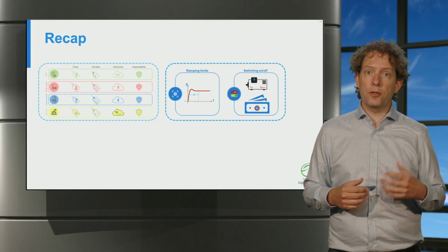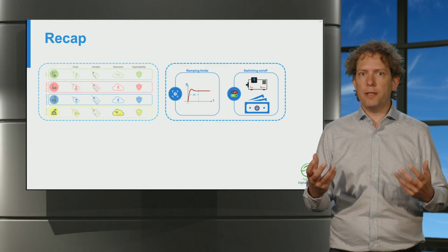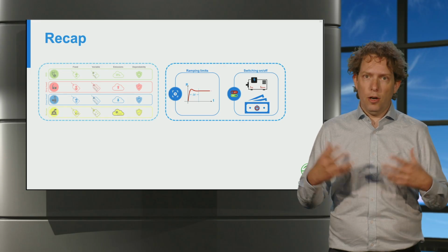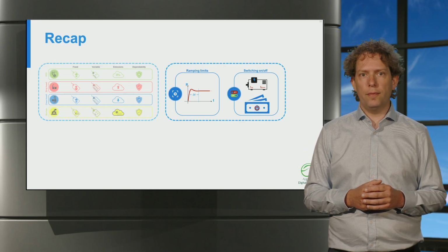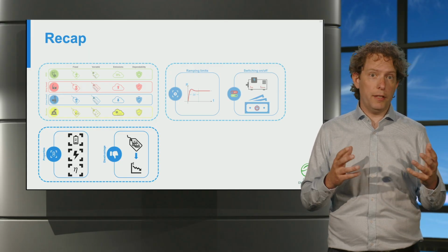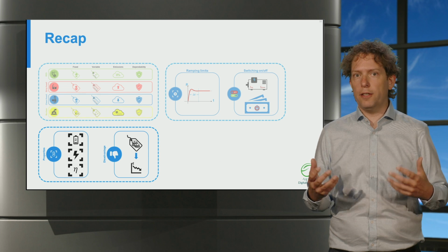Next, I've shown how constraints on the ramping rates and on and off times influence the flexibility of individual generators, and therefore of the system as a whole. However, battery storage can help with alleviating these constraints, for instance by storing energy to use when the demand is highest.